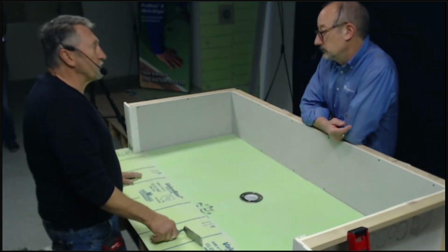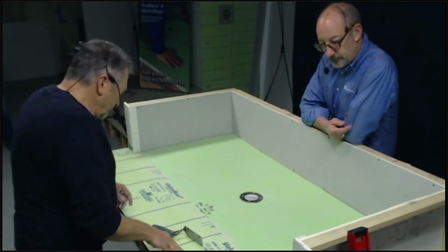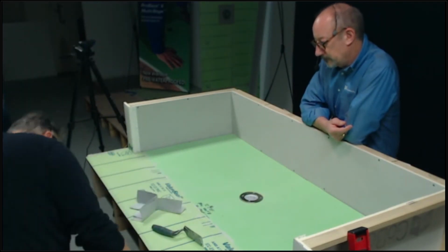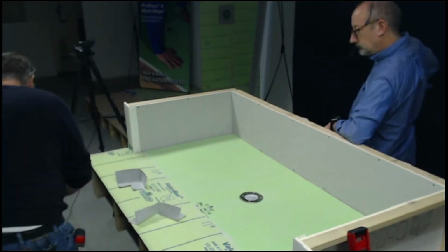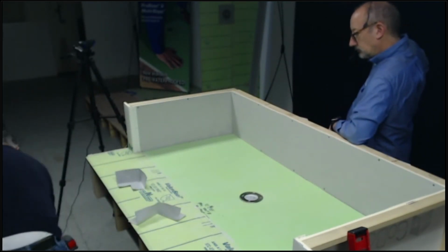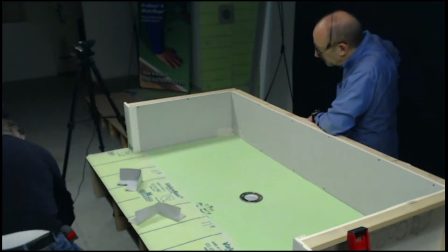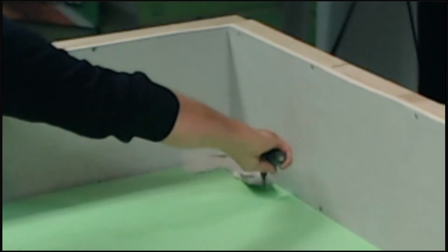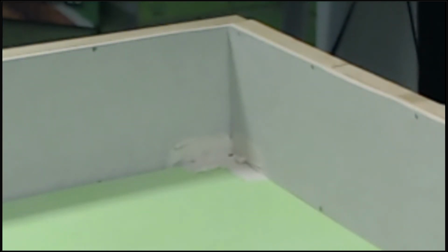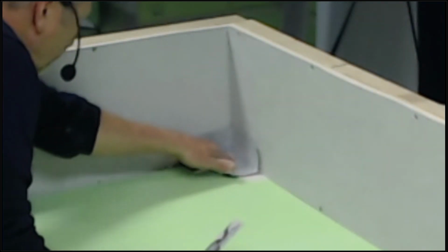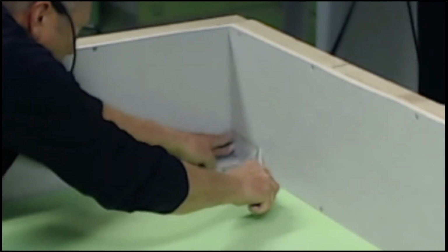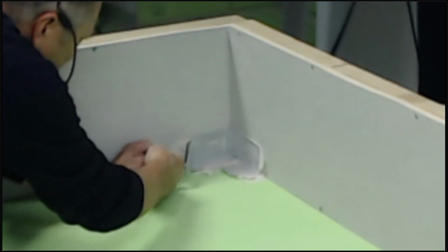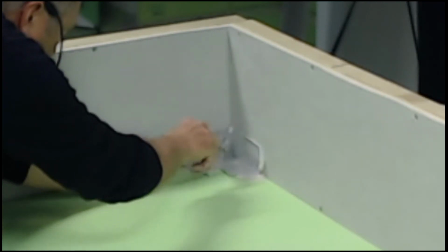Now from here, I'm ready to do my transition from my base to my walls. First of all, I'll use our thin line corners. Got 2 outside, 2 inside corners. So I'll place my outside or inside corners in first. Simply put some modified thin set in the corner. Don't be shy with it. Make sure you have plenty of coverage. Just place the corner in and then tool that out. Make sure that you see the thin set coming out of all the leading edges of the corner and that you have 100% coverage.